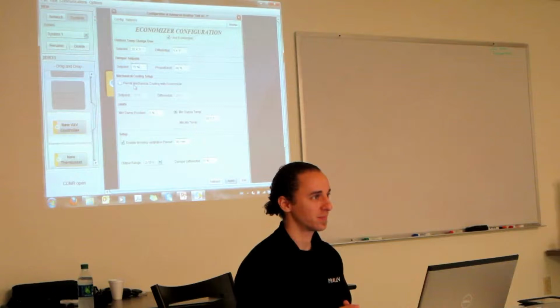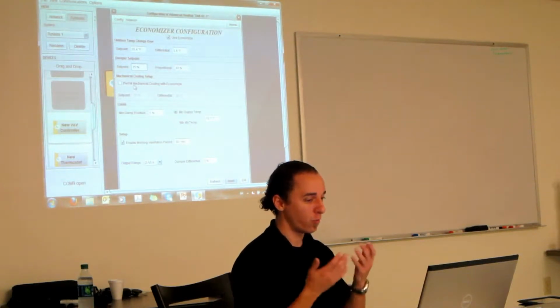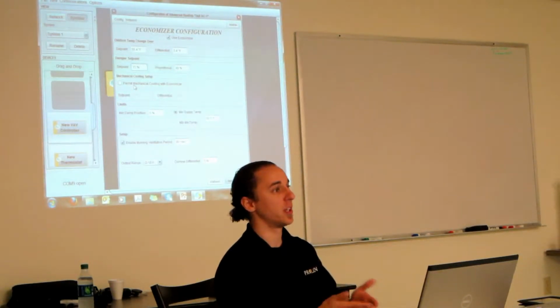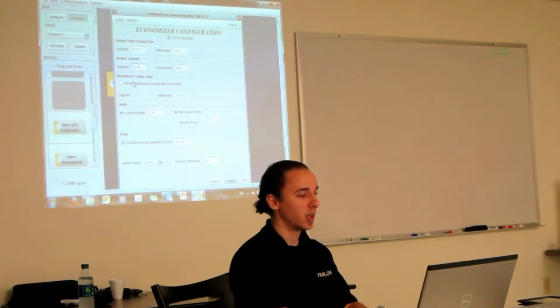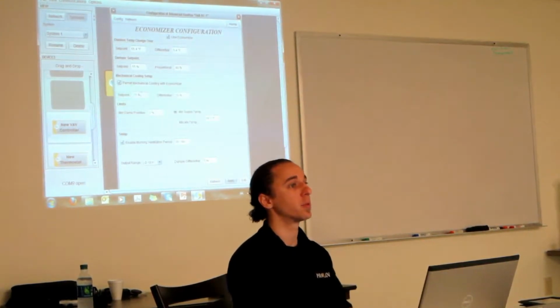Typically I'll run the economizer up to 65, even 70 degrees, particularly if I'm looking at outdoor humidity, because for that reason it's easier to cool 65, 70 degree air than it is to cool the return air at 75. So, well, there we go. So this option is available if you guys want. You can just click it and then just put in your set point and so on.